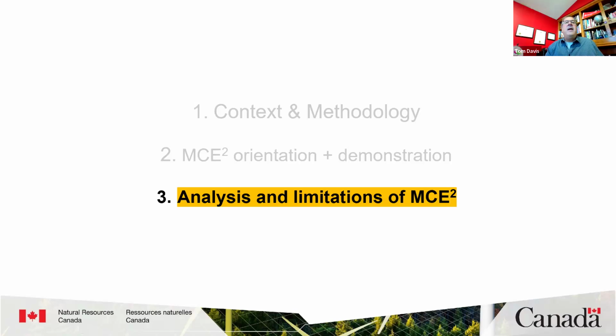I've already talked about Matthew's question about the wool insulation: it does have some sequestration, but both the wools listed are carbon positive. Michael asks: does MCE squared consider the carbon impact of labor, methods, and installation of the building components? No, because it's only looking at A1 to A3. We've got to go through all of the building stages; that would be done as part of a life cycle assessment. Again, we're calculating A1 to A3 with this software.